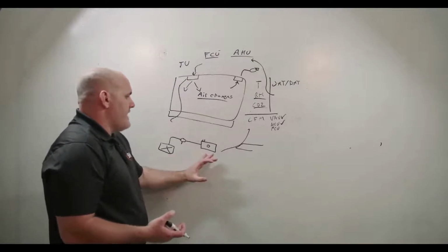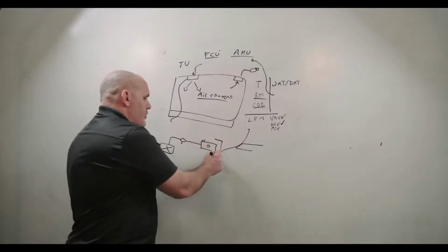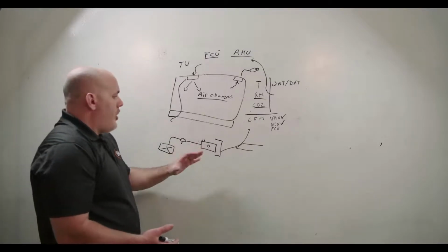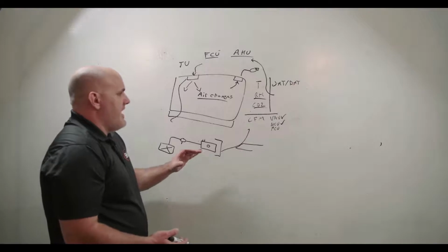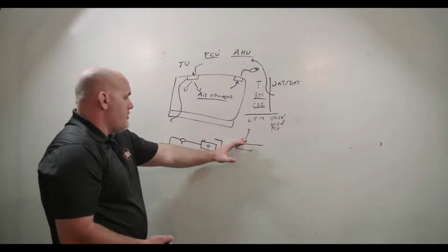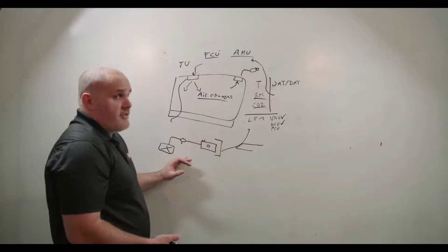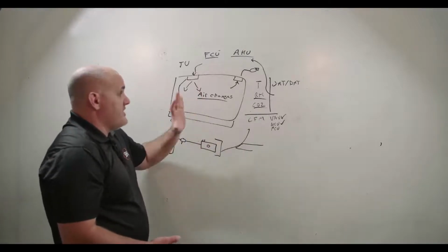But by troubleshooting airflow, you will real quickly determine what your issue is in a space. That's almost always the issue, something to do with airflow. Either a smoke damper's blocked before the VAV box, or something's messed up after the VAV box. If it's a single space issue,